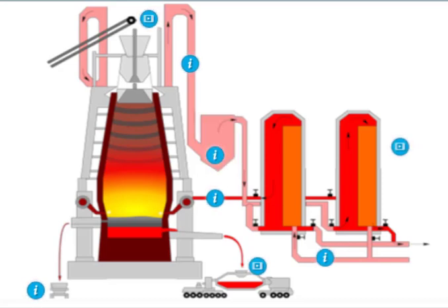The cold main blast enters here, and large volumes of air are generated by a turbo blower and flow through the cold blast main to the hot stove. The cold blast then enters the stove that has been previously heated. All this is preheated, and the heat stored in the refractory brick inside the stove is transferred to the cold blast, making it the hot blast.